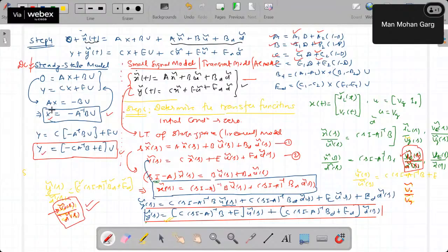Once we got the X value, then we can get Vd = (A1 minus A2)X plus (B1 minus B2)U, and Ed = (C1 minus C2)X. So we got Bd and Ed. All these matrices are required for getting the fifth and sixth matrices or vectors. We need the value of X, which is given to us. Okay, so that we can get. Now once we get it, we can directly use the formula. Let's say we want this V naught upon D, so that is nothing but C (SI minus A) inverse Bd plus Ed. Now everything is with us.